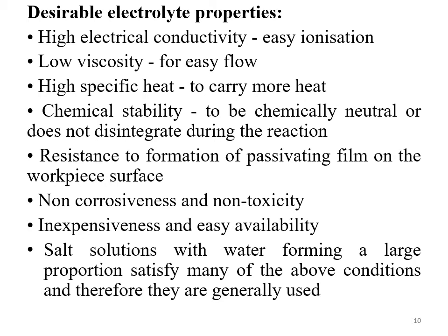Coming to the desirable characteristics of electrolytes. First one, high electrical conductivity and easy ionization. Electrolytes need to be highly conductive to the electrical energy, and once the metal ions get dissolved, the electrolyte should be prone towards causing the metal ions to get separated from their parent surface.